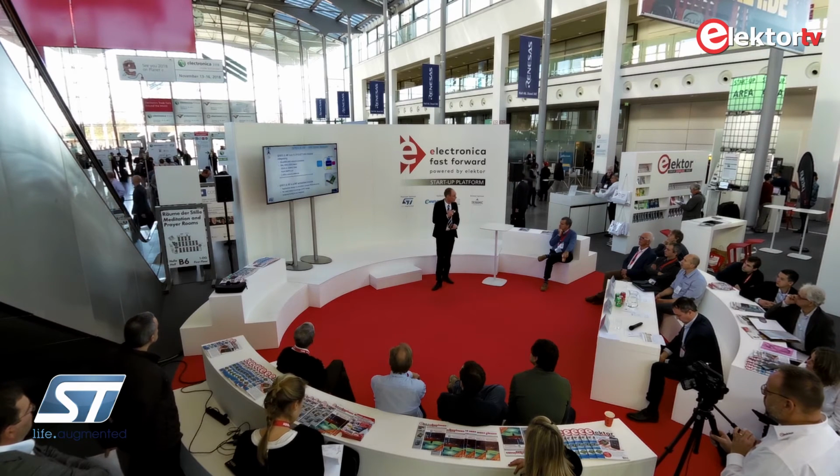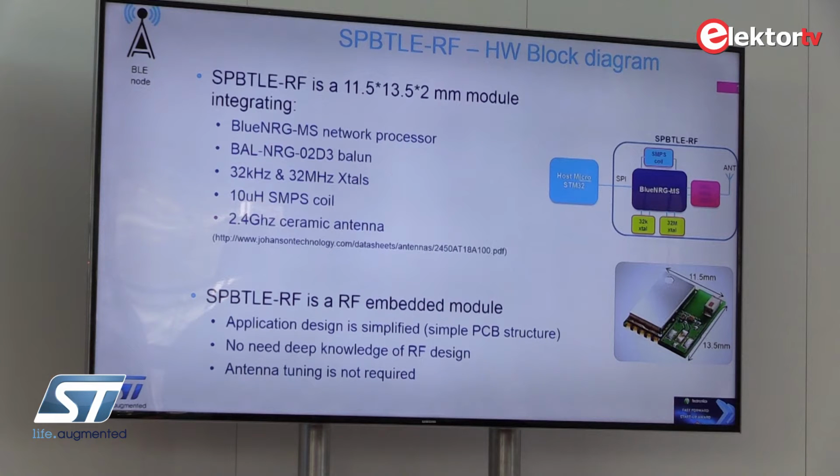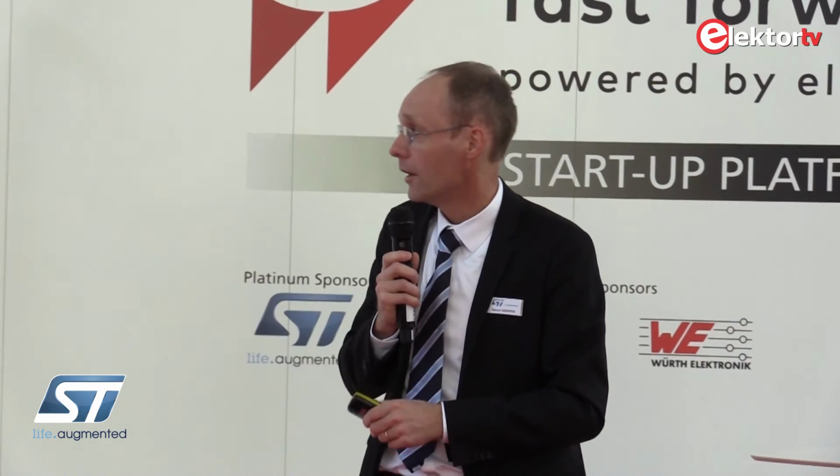You can again go through a module: if you don't want to go for certification and want a fully packaged, ready solution, you go to this module, which is available as well and still provided by ST. Or you go for BlueNRG-1, which is an application processor, meaning that the application this time will not run on an STM32 aside, but will be fully integrated in the system-on-chip package. It is exactly the same protocol stack running, and already available for the mass market.